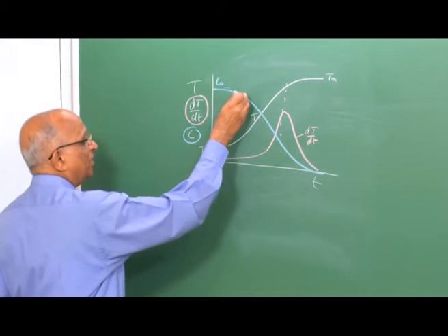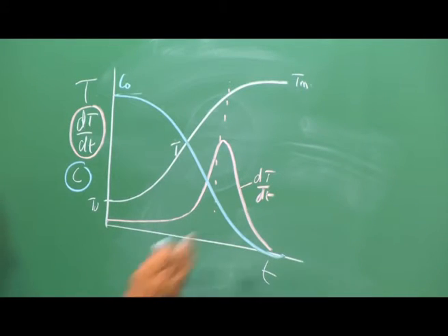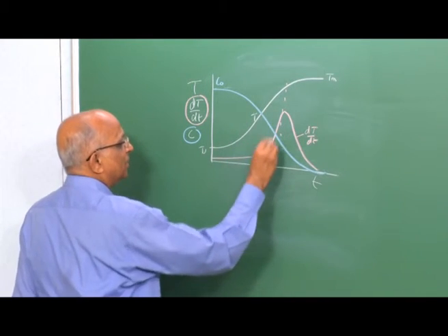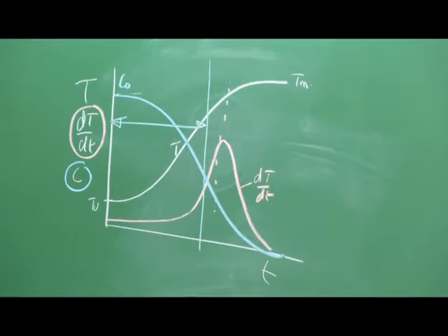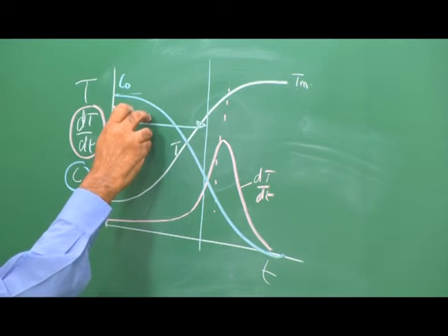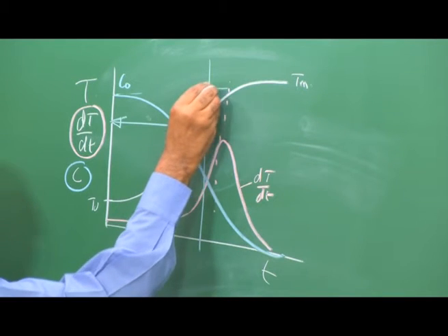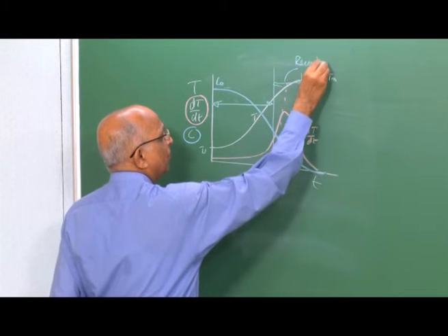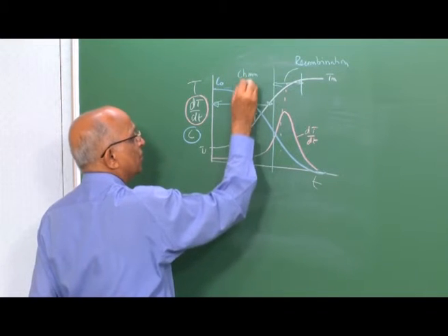Well, these are the concentration plots, the temperature increase plots, and the rate of temperature increase plots. Based on whatever we have discussed for hydrogen, oxygen, and it is true for any hydrocarbon or most of the substances, it is during this period that the chain initiation, chain propagation and the chain branching reactions are there and an avalanche of chains is being formed. During this period recombination reactions take place during the actual time of heat release, that is recombination of chains to give me the heat, and these are essentially the chain formation stage.